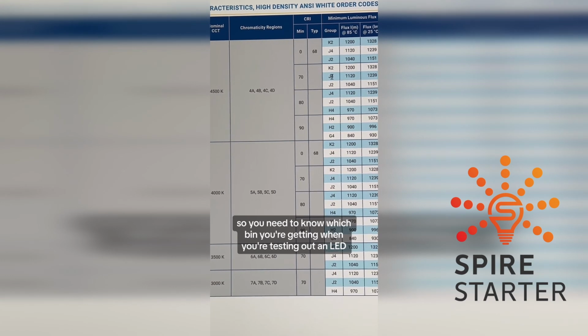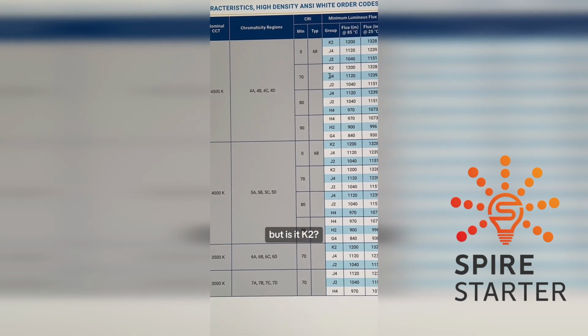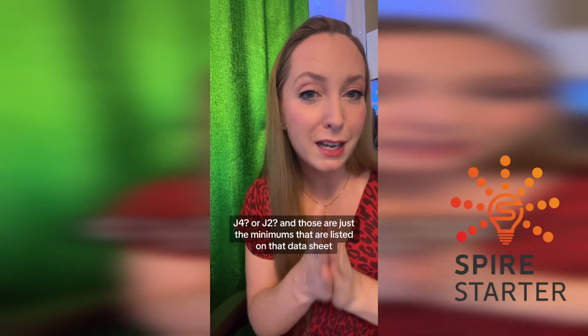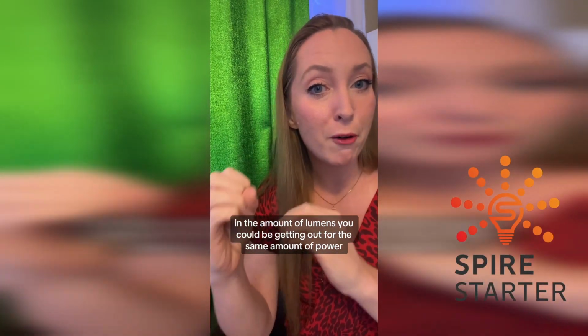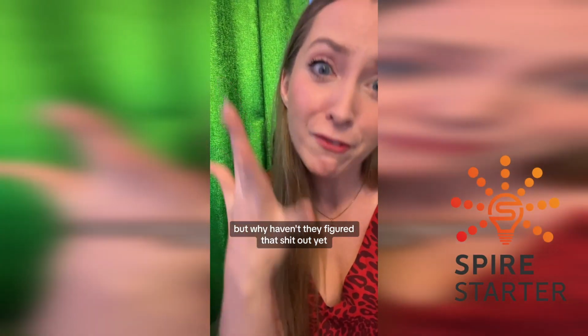So you need to know which bin you're getting when you're testing out an LED, not just color temperature and CRI, but is it K2, J4, or J2? And those are just the minimums that are listed on that datasheet, so it can go even higher than that. There's a very big range in the amount of lumens you could be getting out for the same amount of power when you're taking an LED and sticking it into your system. But why? Haven't they figured that out yet?